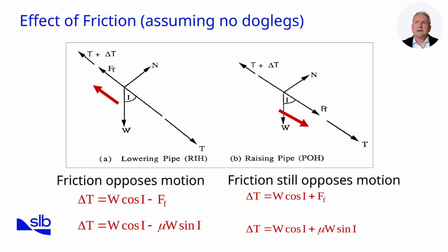The diagram illustrates how frictional forces act during axial pipe movement. On the right, pickup is represented by an increase in hook load as friction adds to the string's apparent weight. On the left, during slack off, friction reduces the measured hook load. This graphical representation highlights the dual effect of drag, additive when lifting, subtractive when lowering. Operationally, the takeaway is that friction always resists pipe movement, and its magnitude depends on borehole inclination, surface roughness, and mud lubricity. Even in straight holes, these effects cannot be ignored.